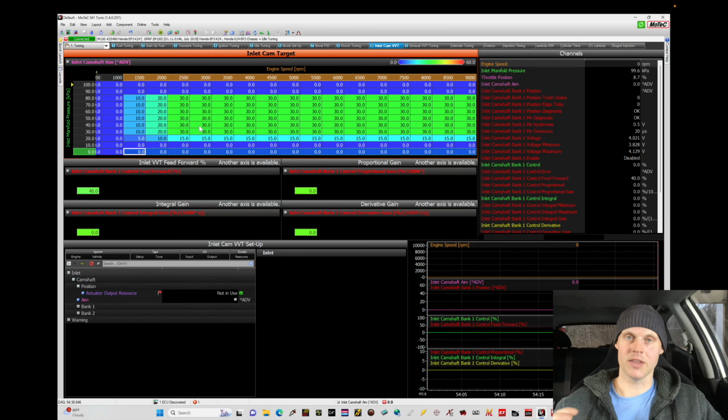As we're rotating the cam and allowing it to actually move and creating that overlap, it's going to put a lot of stress on the timing chain tensioner with a K-Series engine. Other engines are going to respond differently. So a 2JZ VVTi engine, for example, doesn't really matter. I typically zero it out and do this type of function as we're finding right here. It improves the on-off throttle feel for most variable valve timing engines. But K-Series are notorious for beating up the timing chain tensioners with aftermarket cams.